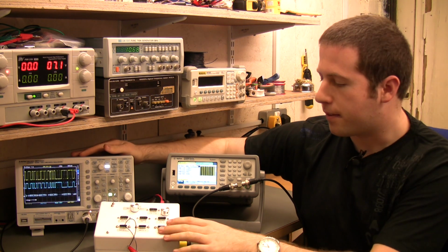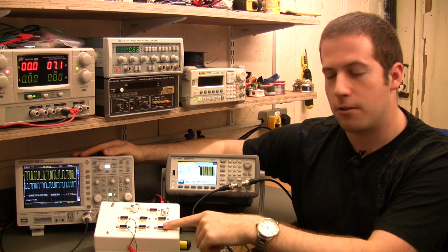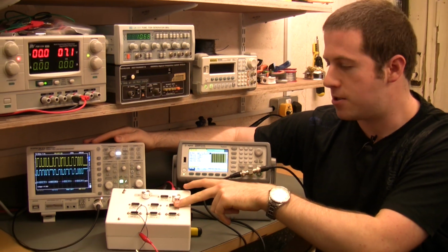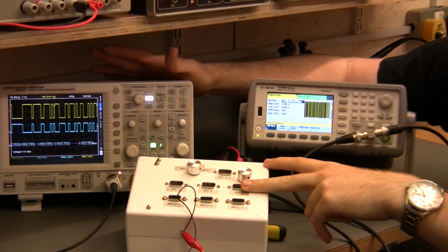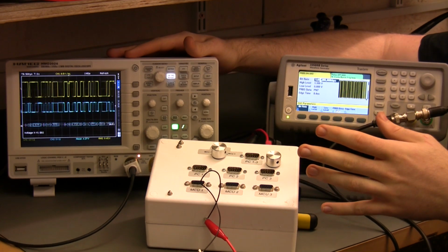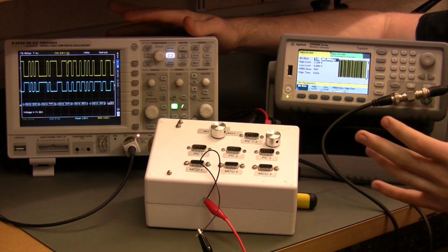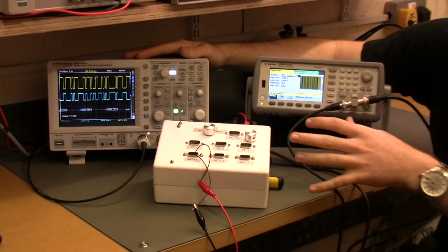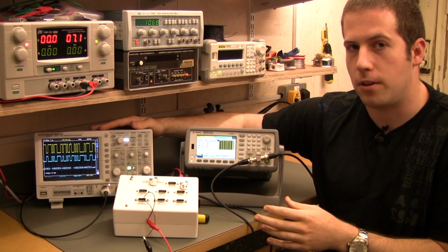So what we've got here, a bit of kit, you plug in a serial signal from a microcontroller, it outputs a signal that's at a proper RS-232 level. So a very basic bit of kit, and it just uses one level shifter IC. So what we can do with the function generator is to actually have a look and see what kind of speed this level shifter IC would go up to.